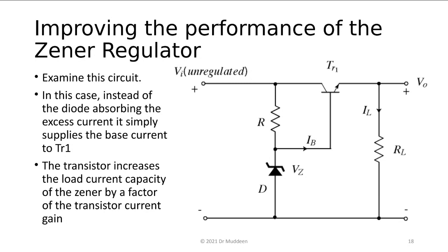You would probably go as close to the design limit as you can, because in our case a half watt Zener will cost a little more than a quarter watt unit. If the end product is only designed to last a few months and is going to be thrown away anyway, you would probably go for the cheaper option, because the economics don't make sense for the better one.